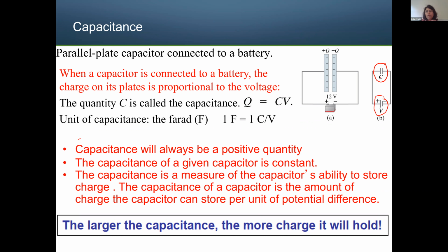C is a manufactured number that is defined by the manufacturing process by changing some variables in the capacitor. But the main equation for the capacitor will be charge equals capacitance times the voltage you're going to apply. So as soon as you see it in here, C will be Q divided by V. Q is in coulombs, V we're going to measure in volts. Coulomb over volt, we call it farad. Farad is the unit of capacitance.